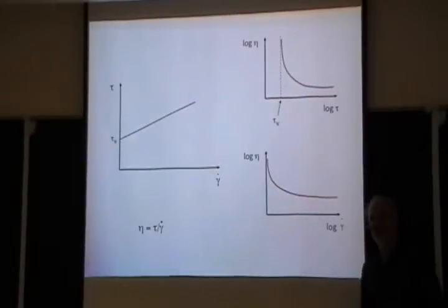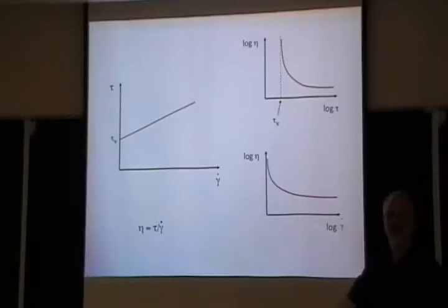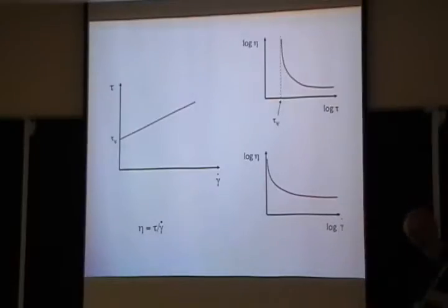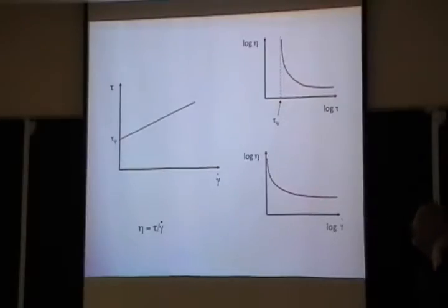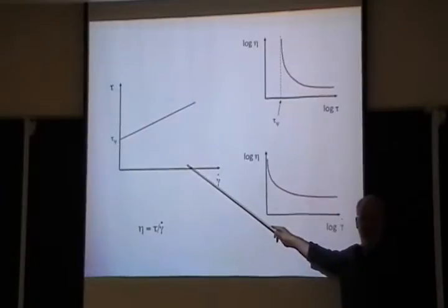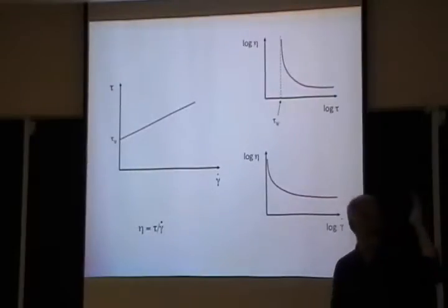But why am I talking about shear stress? It's just really simple, because in the rheology community, people have a rheometer, and what they measure is shear stresses. And just recently they all woke up and decided to look at normal stresses, but typically you do shear stresses. So let's just play with shear stresses a little bit. I mean, it's true actually, we need to work on it. What I want to show you a lot of now is plots like this on a log scale, because we're going to go over many decades in shear rates, many decades in stresses.